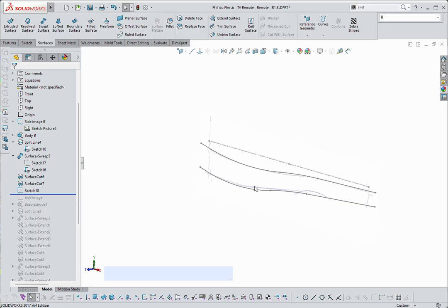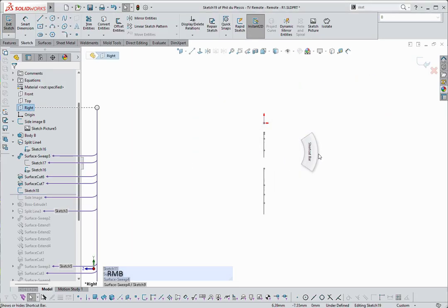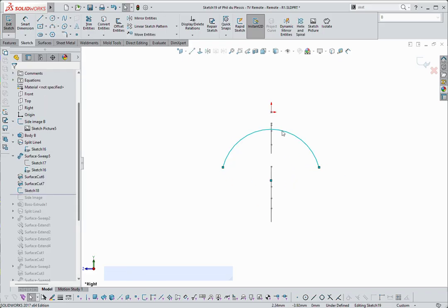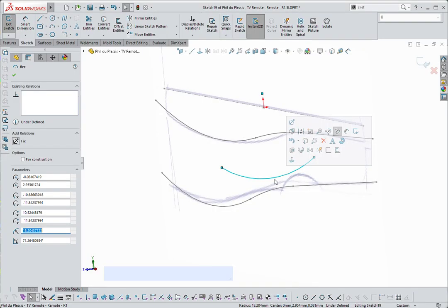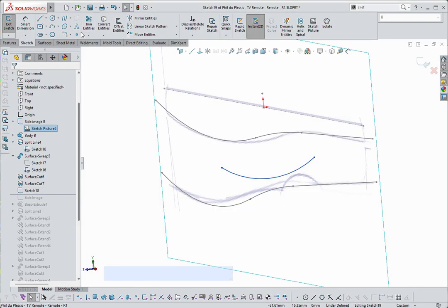And I want to put another sketch inside on the right view. Okay. So it's just going to be a curve, something like this with, nope, that's not right. I want it to have a belly. And now I want the center point of that line to connect with this line here. And so in class, what I'd shown you to do is to use the point.